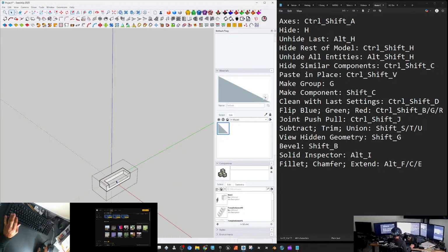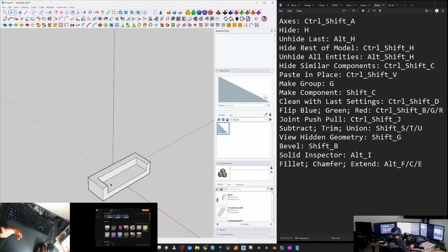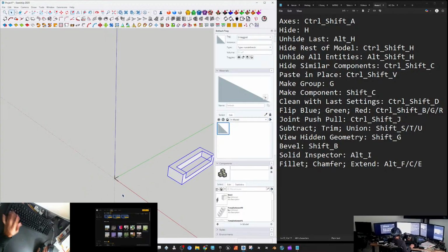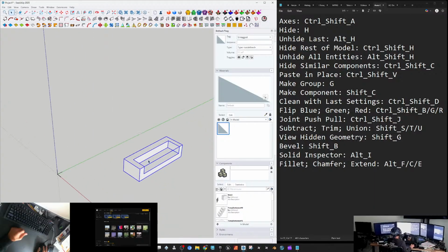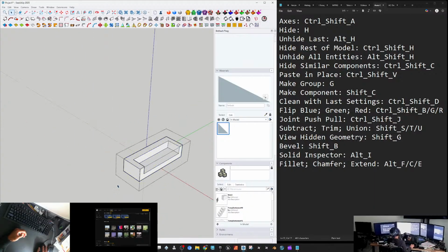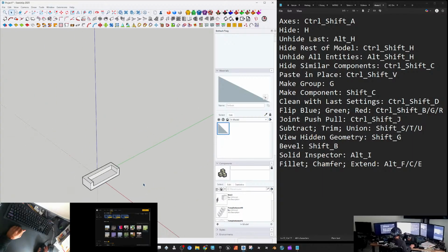But let's undo that. Let's say I click out of the group and then I move the group itself. So when I double click into the group, my world origin actually moves with the group. So things to consider, because when you bring these models into Unreal Engine, the origin location and the location of the gizmo will be correlated to the origin location of the group.